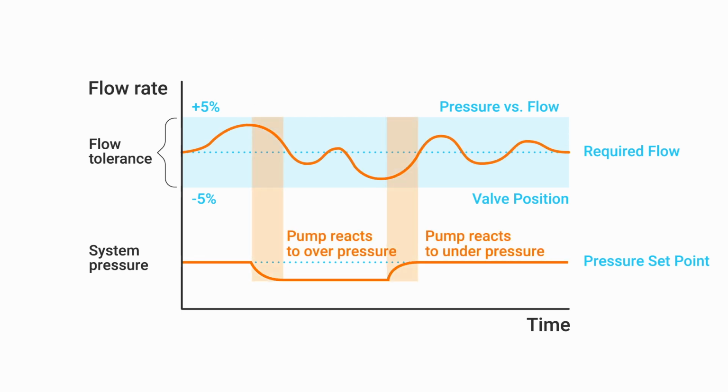This technology is being rapidly adopted as it offers real-time flow rate feedback either to the DDC or directly to the BMS. This is a real win for balancing and commissioning. It also allows 100% flow verification at handover and permits continuous or seasonal commissioning. Installers really appreciate this technology too. As valve position is dictated by pressure and flow, simply standing next to the valve, you can see if it's satisfied. This allows early verification of pipe work, even with temporary pumps. Changes can be made and verified at any time, offering complete peace of mind to the entire project team.